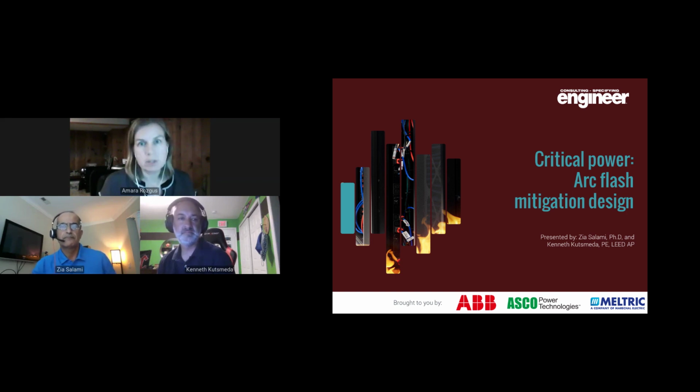Zia, this next question is for you. What information is necessary to calculate an arc flash rating? How do you tell if software is outputting the correct arc flash information? Again, another good question, and the challenging one is at least the second part. But let's just start with the first part. I think during our presentation, we mentioned the parameters that need to be used to perform the arc flash incident energy calculation.